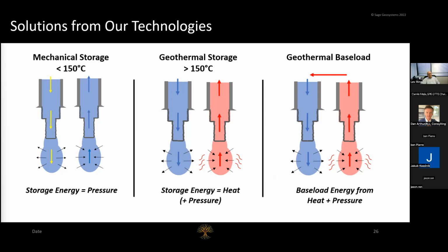So you pump in and then you produce, and you put a mechanical turbine like a Pelton turbine, and you can convert it to electricity. And we tested efficiency, and downhole efficiency was around 90%, which gives a round trip efficiency of 70%, which is very good. It's actually very competitive with pump storage hydro, which is 95% of all global storage capacity.